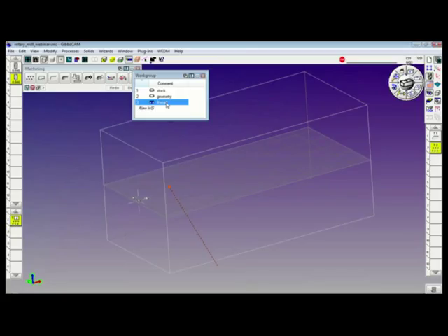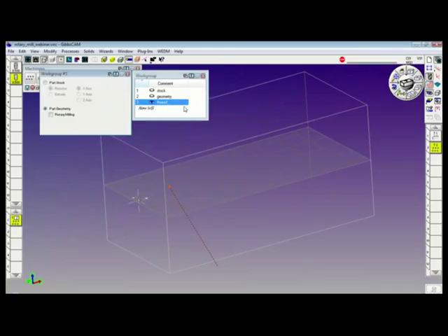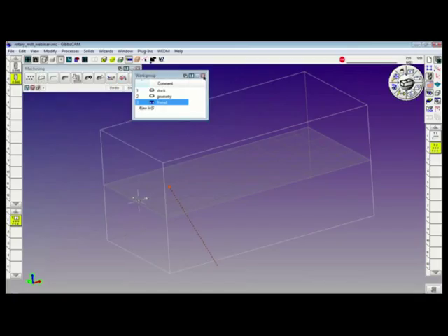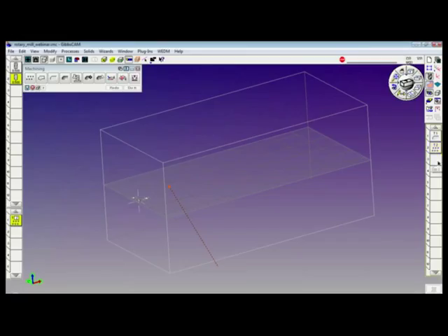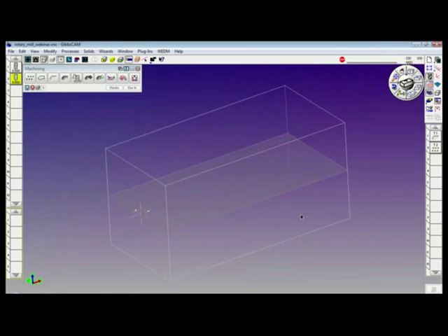So I'll right mouse click the work group, go to WG Info, select Rotary Milling, close the dialog, and deselect the operation, throw away the process, and draw some geometry for a thread.